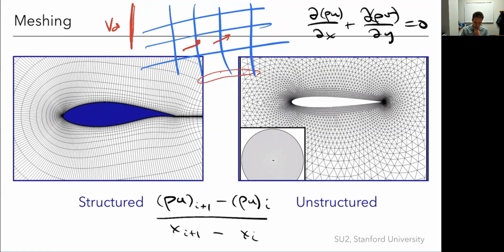So I could look at the fluxes of momentum and mass coming in. I just use these same equations. So I'd have like some rho u coming in, a different rho u coming out, and I just apply the equations on this little tiny volume. And again, I apply that on every tiny little volume. They're all related through this big, huge linear system of equations I solve and iterate, and so on.